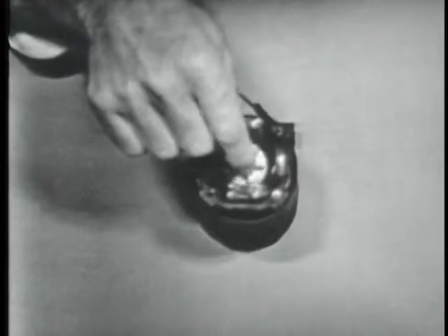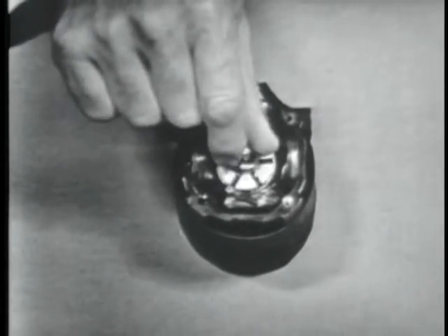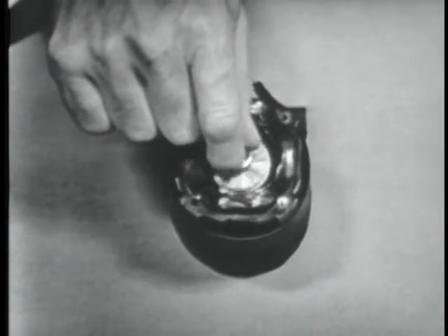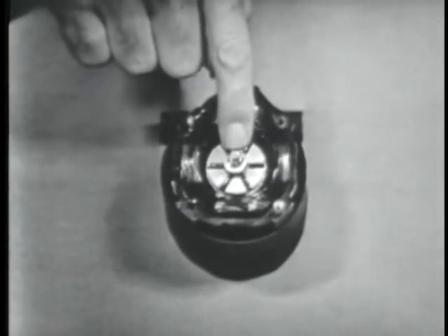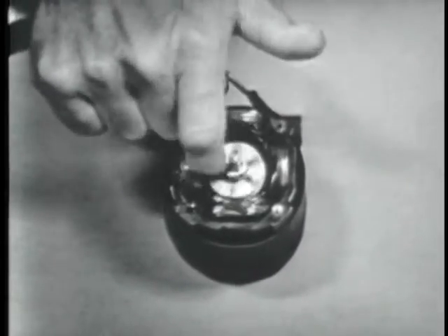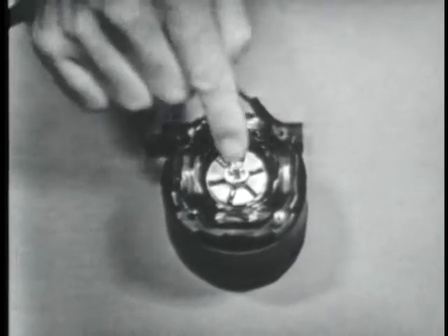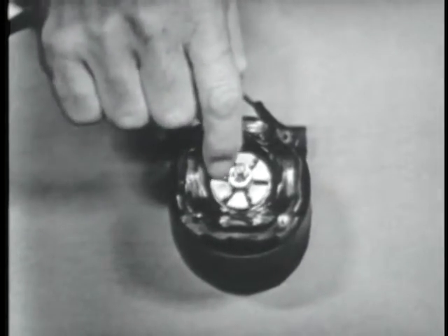Now, what do we mean by that? Internal loading refers to the drag or the load on the motor caused by weight and friction. You mean like it would be easier for a little guy like me to push a small light car than it would to push a big old heavy clunker like yours? It'd be easier for anybody, Tom. Especially me. Right. The same thing is true of this rotor. That is, it takes a certain amount of energy to overcome its weight to cause this hunk of iron to turn. And, of course, the friction of the rotor shaft on the bearings adds to the internal load. And there's a little cooling fan built into the rotor, and that increases the internal load.